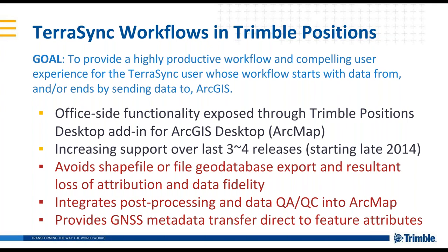And we've done that through this Office side functionality exposed through the Trimble Positions desktop add-in for ArcGIS Desktop. It is for ArcMap. We've gradually increased support for these workflows over the last 3 or 4 releases dating back to late 2014. Fundamentally, the reason it's advantageous is it avoids any shapefile or file geodatabase export and any loss of attribution in the process, or names getting truncated or things like that.